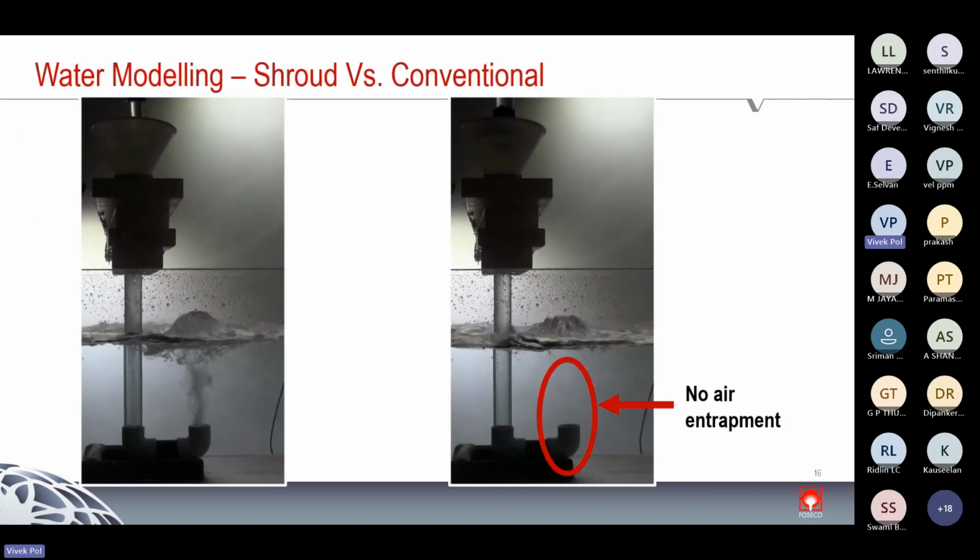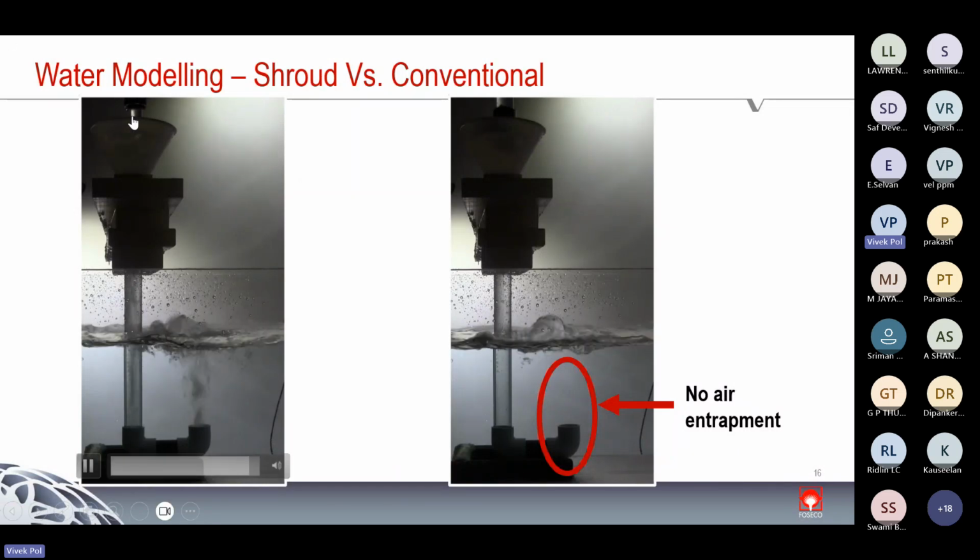That is one part, where we are taking metal from the furnace, and now the second part is we are pouring from ladle to mold, and you can see the difference. We are talking about bottom pouring ladles used in steel foundries. So conventionally, you can see on the left side, conventional bottom pouring, and the air which is getting in along with the metal, and how much turbulence and air reoxidation is taking place.